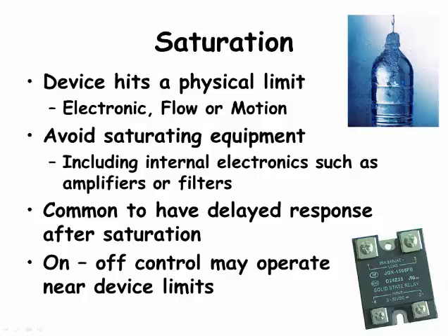Devices that have been saturated usually will experience some delay in their response. So if you have a saturated amplifier, it will take some time before the amplifier will respond properly after the input signal drops below the saturation limit. On-off devices like relays can operate near their limits. The relay shown can handle loads up to 25 amps and 240 volts AC. That is equal to 6,000 watts or 6 kilowatts. You should be able to use this relay to handle a load near 6 kilowatts without difficulty.